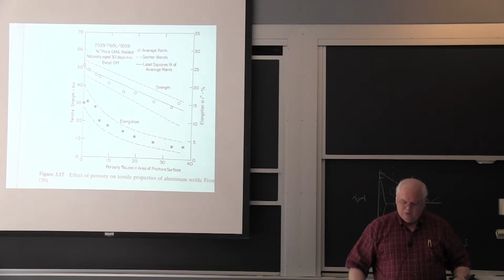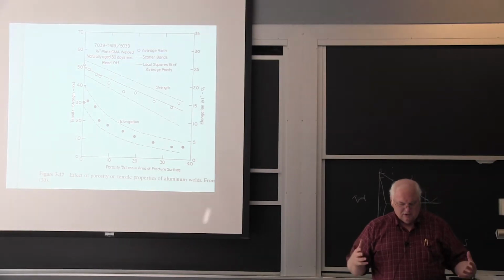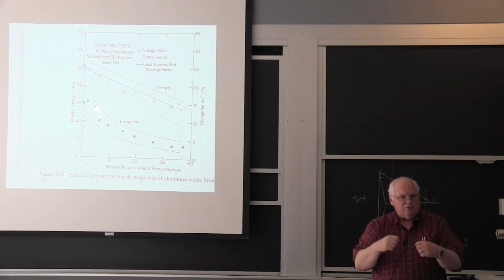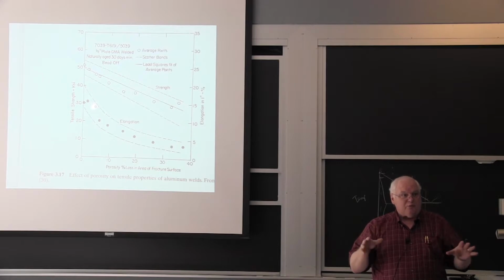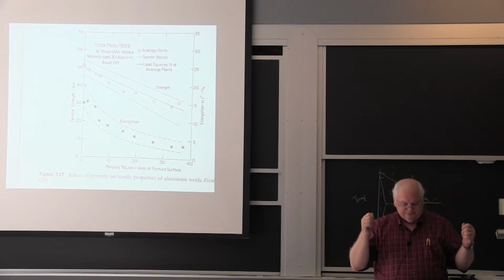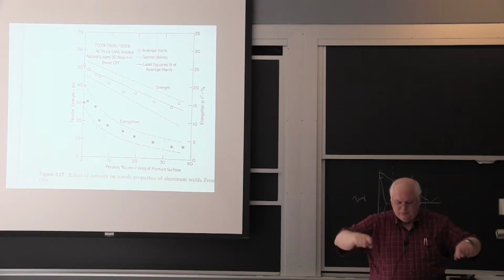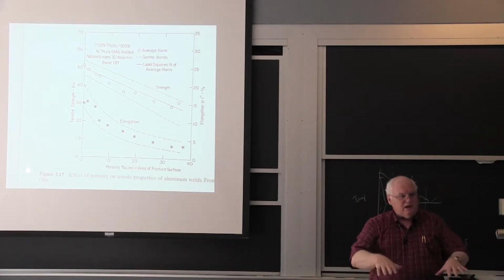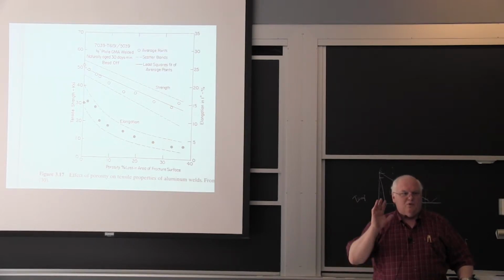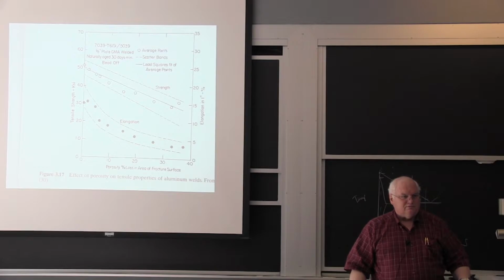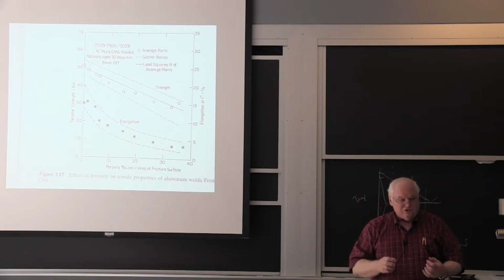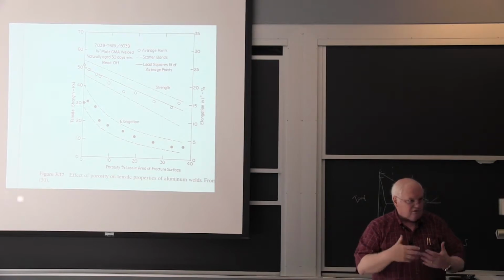And I remember it was White Plains, New York, and I was on the witness stand, and I was trying to explain how little this porosity was. And I think I'd ripped my piece of paper and shown them a brittle material. And aluminum's not that brittle a material. It's a ductile material, particularly this type of casting that it was made out of. Turns out the witness box had a little table that was about 4 feet by 3 feet. I said, it'd be the equivalent of having 5 ping pong balls on the table. And it was. I'd done the calculation, the porosity in the area of the little turnbuckle.